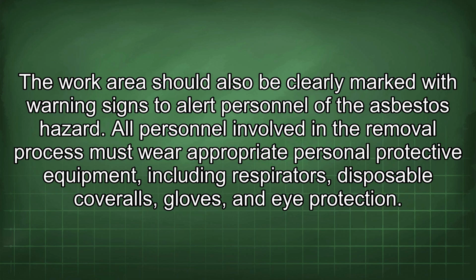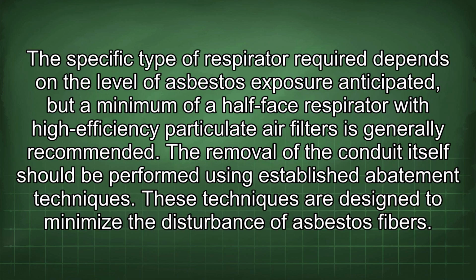All personnel involved in the removal process must wear appropriate personal protective equipment, including respirators, disposable coveralls, gloves, and eye protection. The specific type of respirator required depends on the level of asbestos exposure anticipated, but a minimum of a half-face respirator with high-efficiency particulate air filters is generally recommended.